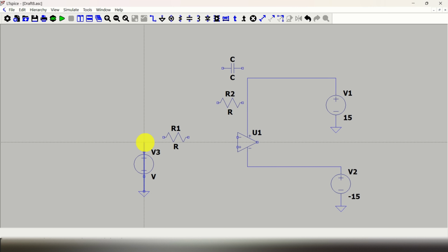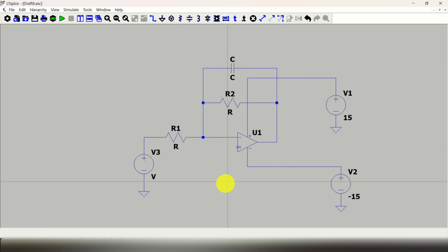So click here, and connect this to the inverting input. Do the right click, then let's create the feedback. Go from here, click here, click here, click here, and here. And then let's do the same thing for the capacitor, connect it to the feedback loop, and here it is. Perfect. Now we have our capacitor, R1 and R2 resistors, and we just need to ground the non-inverting input.